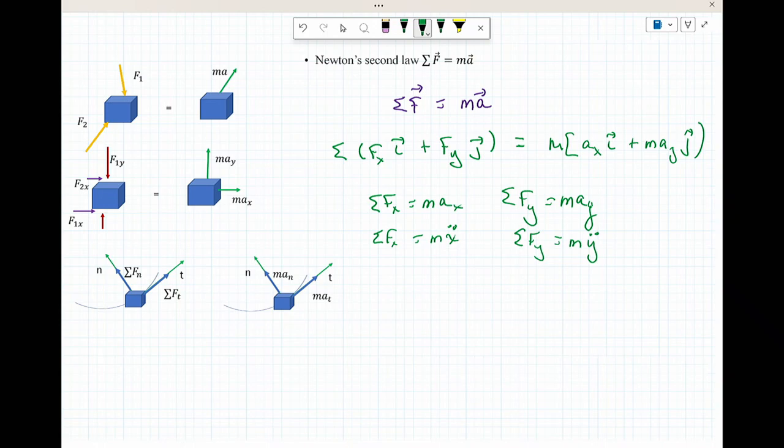Those are our diagrams. So you see the second diagram down on the left. You'll notice force 1y. There's another force 1 or force 2y in there that I haven't properly labeled. Force 1x, force 1 or 2x. You can add all the forces together, and again, the tricky bit is not to solve the equations. Once you have the equations, you're set. It's just putting together the right free body diagram. So that's where you start.